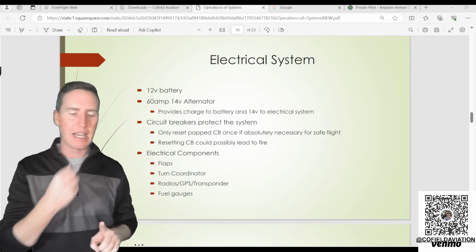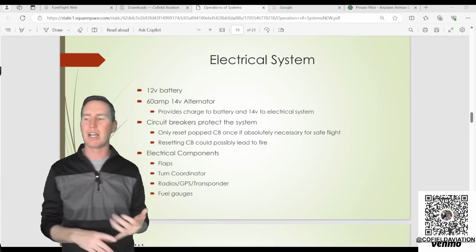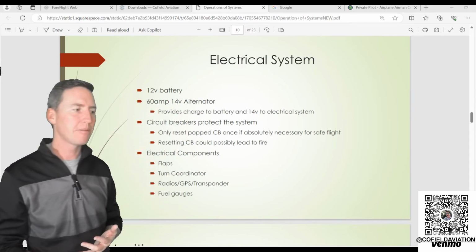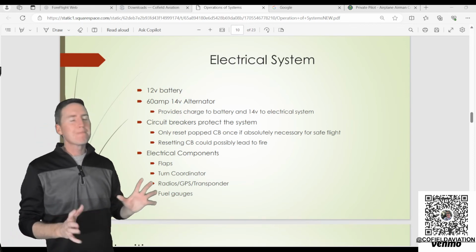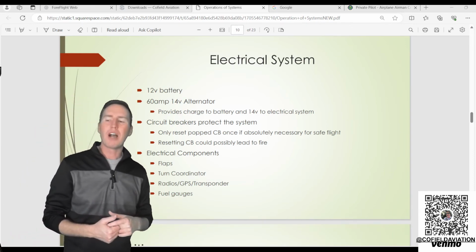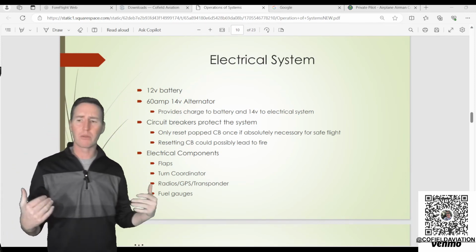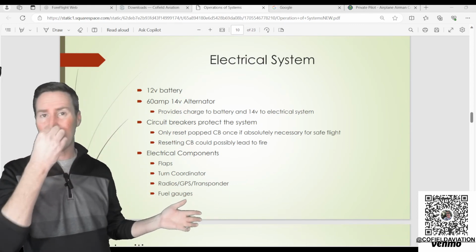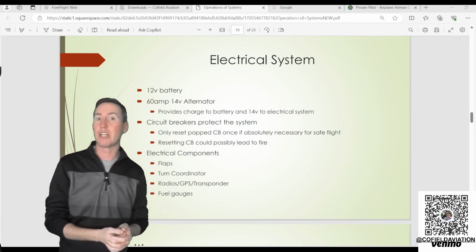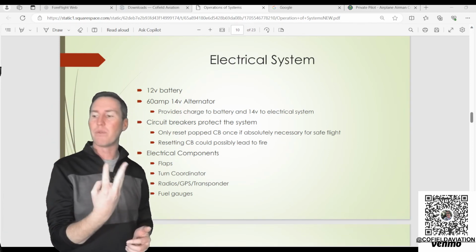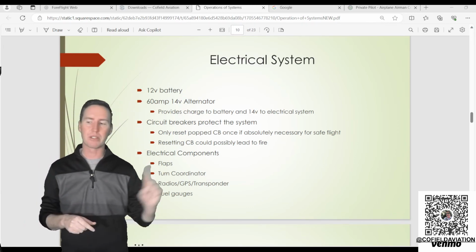All right. That would greatly depend upon, I only have one alternator. I don't have redundancy there. So if I'm flying at night or in IMC, instrument meteorological conditions, and my alternator goes out, okay, or the circuit breaker pops, okay, I'll probably try to reset that because that's fairly important, okay? And especially in the R172 because we have an electronic mag. So now losing electrical power would mean that we're losing a redundancy to the fuel, fire, and air, right? And if we ever lose that redundancy to fuel, fire, and air, I'm getting the airplane on the ground, okay? I'm declaring an emergency.